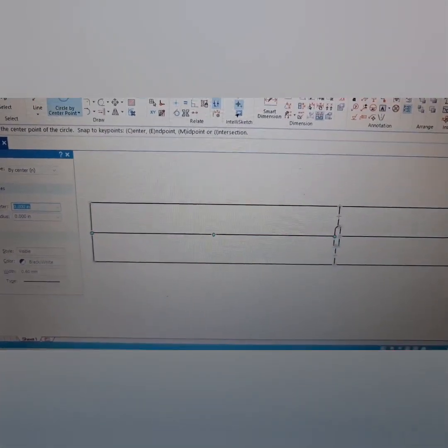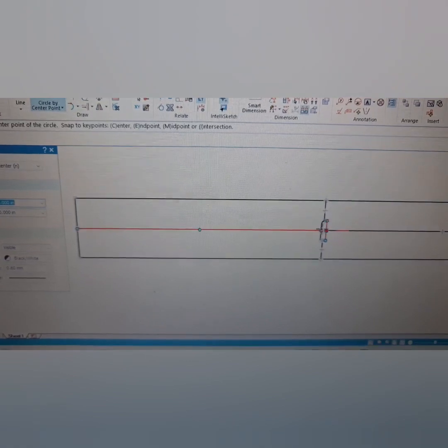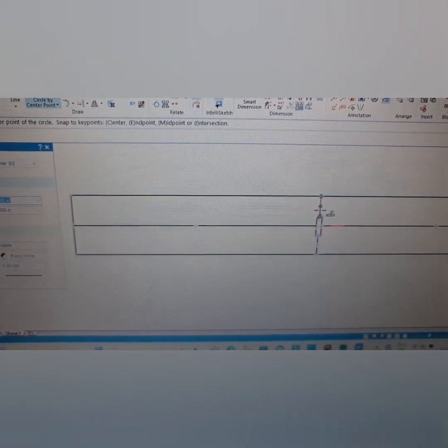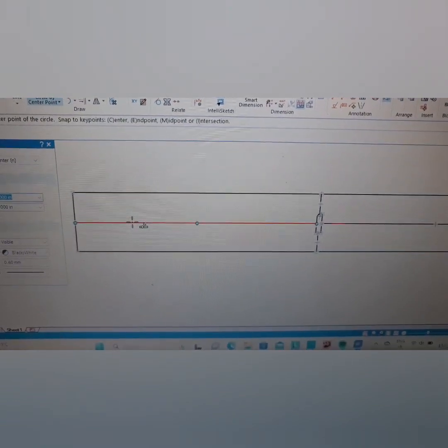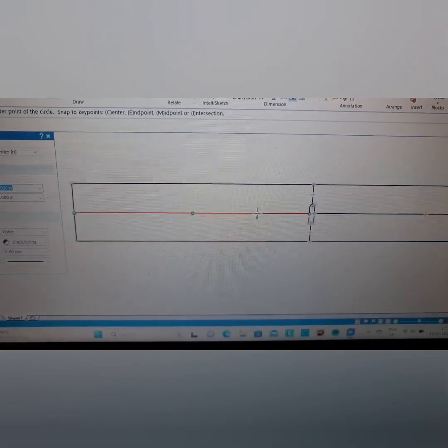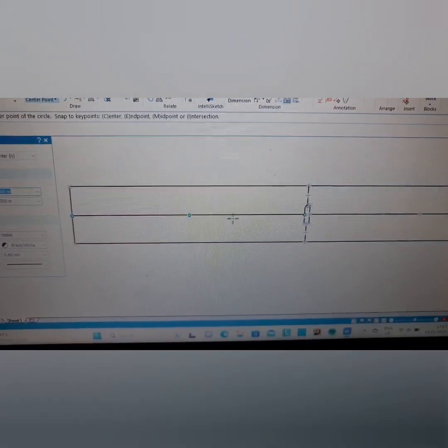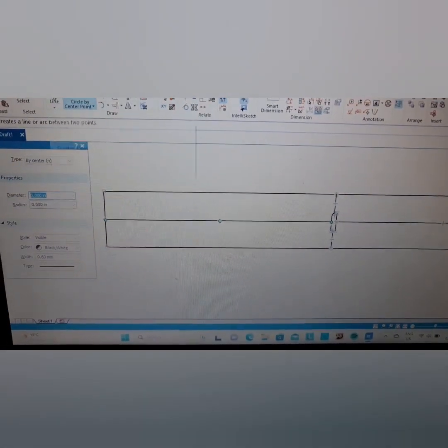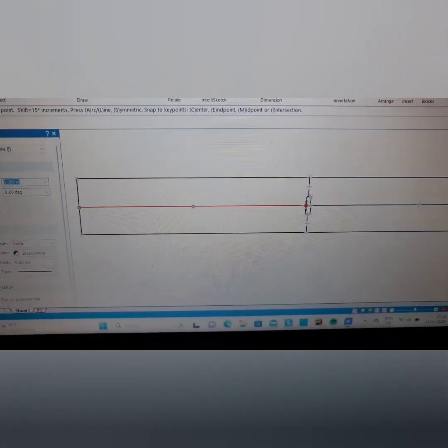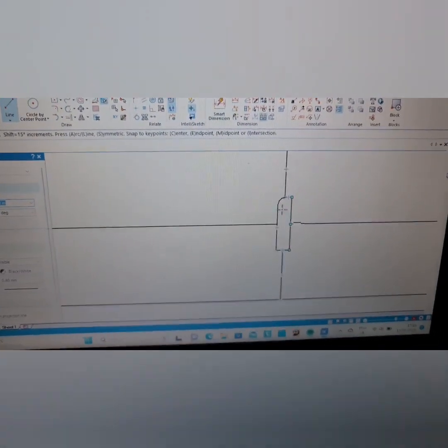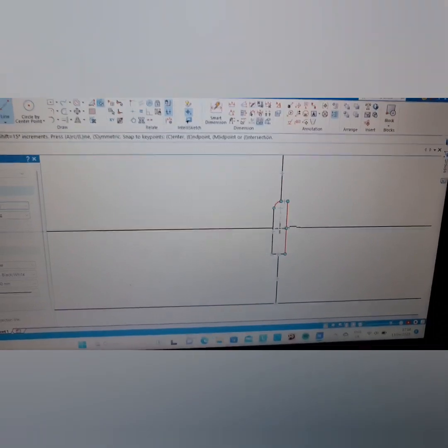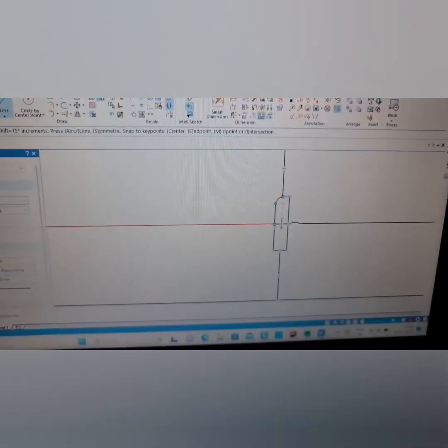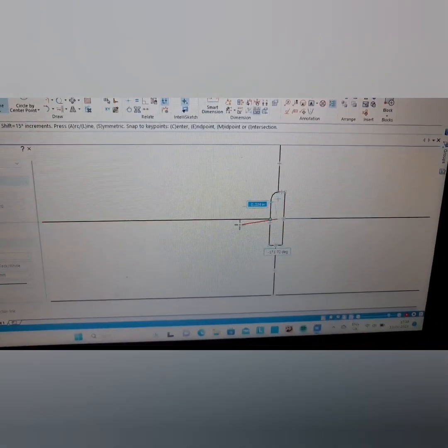So if you go, oh, it's, I don't know, it's 3.5 inches from there out on this center line, there's two ways you can do it. Well, no, there's really one way I like to do it. Get a line, come in here, down there. Now you see it's putting this dotted line in, that's going to plonk it dead in the center.